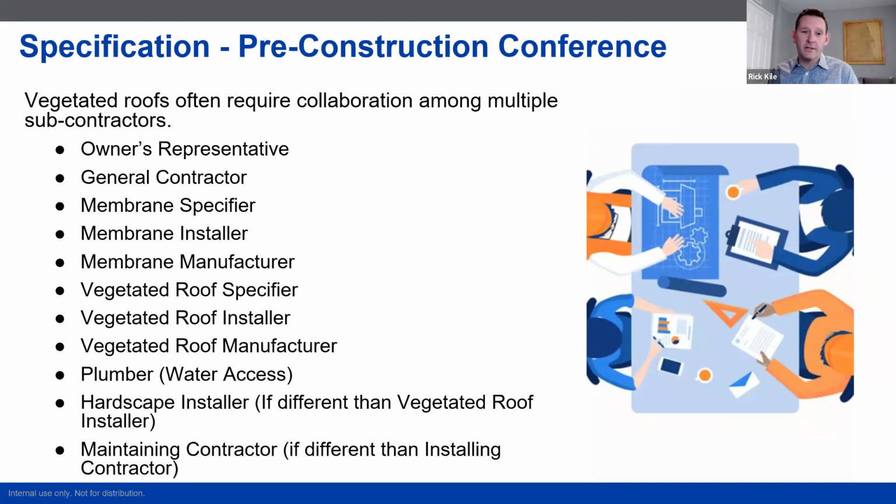Of all the things we talk about, what's maybe the biggest miss, but this I would implore you, most of you probably already know: you can include a pre-construction conference in your specifications. Do it. I've been a part of a lot of pre-construction conferences where having everybody around the table when it comes to a vegetated roof really helps ferret out a lot of the problems that would happen. And it's a pre-construction conference before the membrane goes down, not just before the vegetated roof goes down. And so having everybody around the table able to discuss some of the project-specific coordination points is really critical to success.